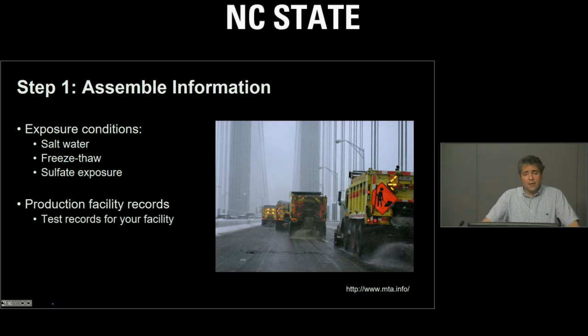And finally, we need to know a little bit about the facility that will produce the concrete for us. Does this facility have a record of producing such concrete before or not? If they have, how much data do they have and how long have they been producing such a concrete mixture? So really, that is the entire material that we need to collect in step number 1.